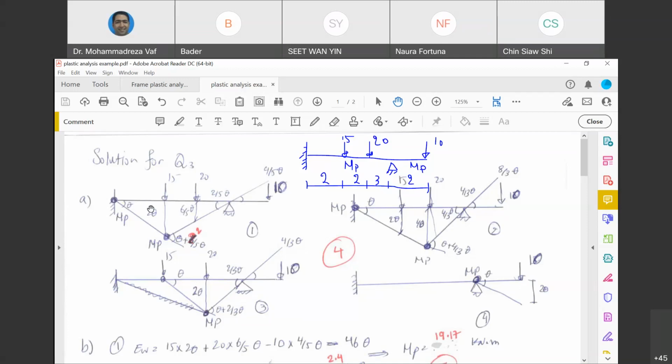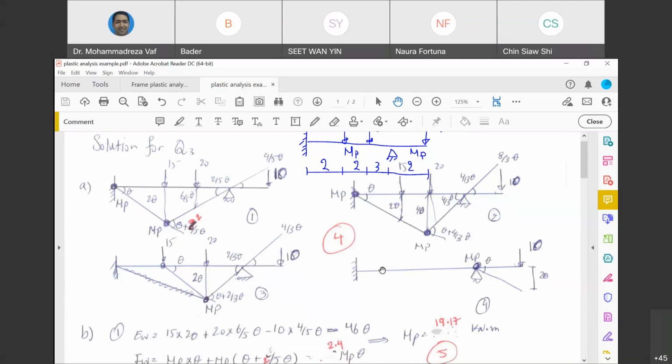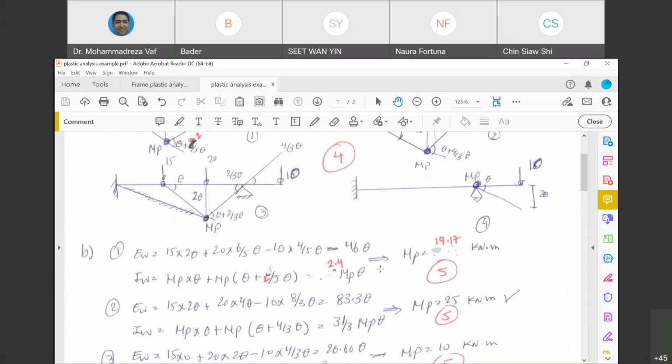Therefore, you need to look at your span and see how many hinges are already there. Since this is a pin support and it is a cantilever one, it can rotate. If it was continuous, it would be a totally different story. So one of the hinges is already there, and you need to have two more hinges. One of them is in the support, one of them under this load. If you say one here and one here, that means you have 4 hinges, because one of them is already there and another 3 you are making. Oh, okay. Understand. Thank you. Okay, any other question?